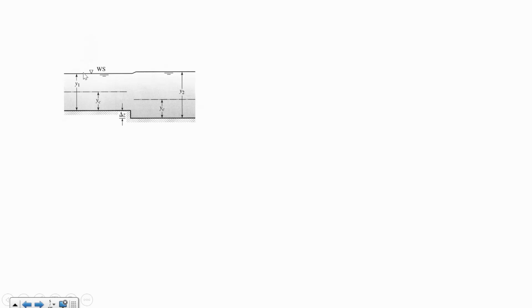We have a non-uniformity in flow, and it's subcritical upstream of the step down. You can also see that what they're saying is that it's going to be subcritical downstream. And that's one of the first lessons to draw from this: the upstream conditions oftentimes are going to govern what happens downstream. So here, since it was subcritical upstream, it's going to be subcritical downstream.